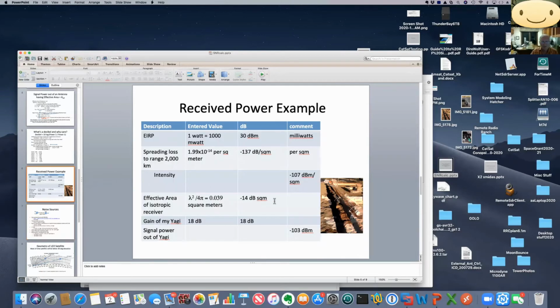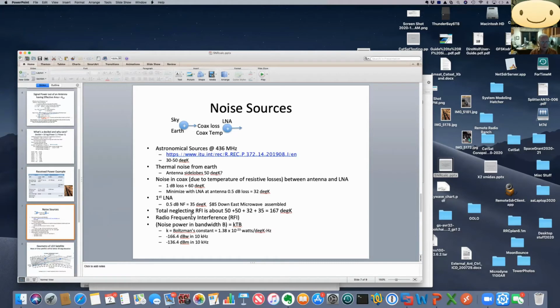I don't think you can see it on this, but at the back of this antenna, the low noise amplifier is sitting right there, at least on my antennas. And so it gets you back to a low loss, which means that the coax cable is not going to be a significant factor.